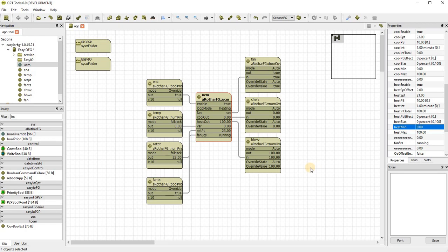There is no proportional component directly applied to the output when this PB effect, both in heating and cooling, is at 0. I know a lot of other loops are fixed at 100, but you can ultimately have this at 25 or 100 or 200 or 0, and you can't go below 0.